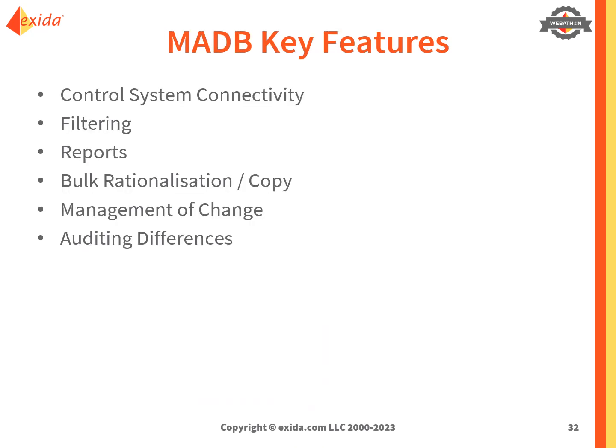So I'm going to talk about the master alarm database key features that are so useful when rationalizing alarms, particularly in the way that the tools like SIL alarm can record the alarms and their attributes in the master alarm database. We can use SIL alarm to take that information stored in the master alarm database and put it into the alarm servers within the DCS. We can use the filter tool to focus on a particular group of alarms like diagnostics, or all the digital alarms, or all alarms from a particular part of the system.